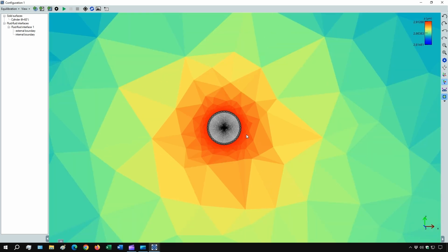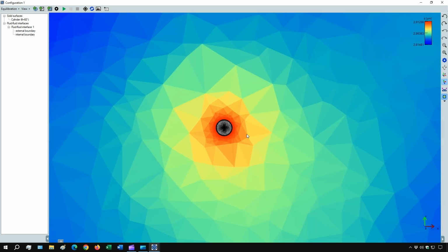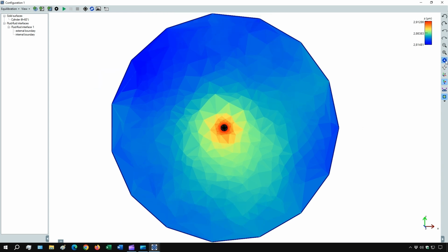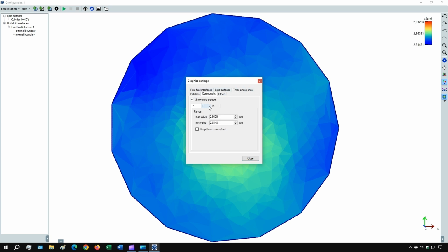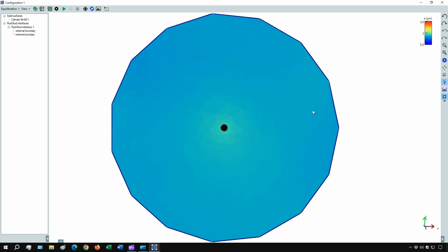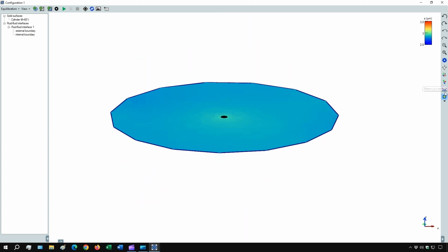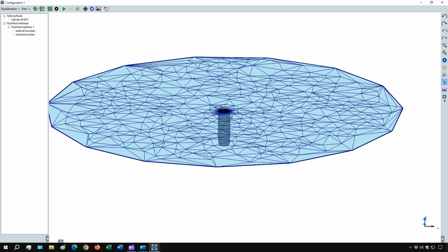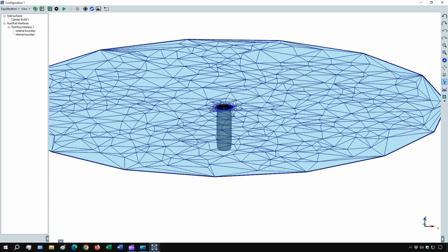There is still a very small deformation near the cylinder, but this is very small compared to the scale of the system, as we can see by zooming out a bit, the scale of the height contour plot. If you were to run a new equilibration with an even more refined mesh, the obtained equilibrium shape would likely be even more flat. This result tells us how the cylindrical particle would stay adsorbed at a flat fluid interface if the particle was fixed in its vertical orientation.